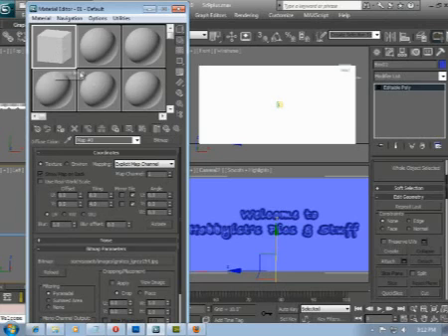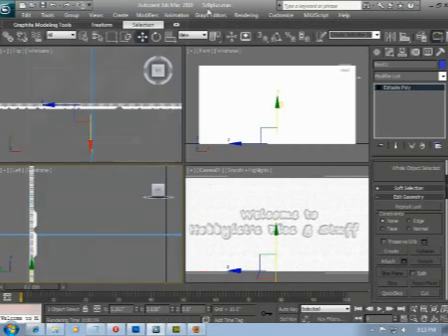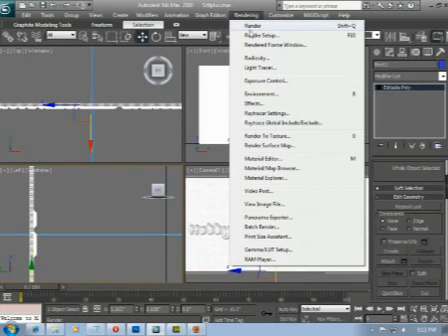Okay, well, let's do it. We drag the skin onto our box in the camera viewport, and the sample slot borders show we made a good connection. Let's hit Show Map in Viewport. Okay, the lighting looks pretty close already. Let's close the material editor and render one. From the rendering menu, pick Render.